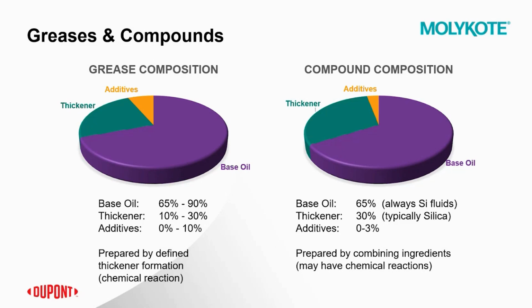And ultimately, it's important to consider the fact that additives can interact with each other. So they could either undergo synergism, where the total effect is greater than the sum of the effects independently, or antagonism, where the observed total effect is less than the sum of each additive individually. For example, that kind of antagonism can occur when you combine anti-wear and corrosion inhibitors with friction modifiers. One additive can ultimately mitigate the effects of another additive.